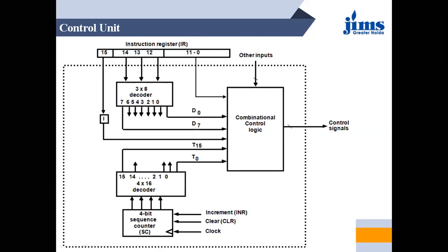See, from here, instructions register, when we are talking about the opcode, then in opcode there are 3 bits, 12, 13 and 14, and by the combinations of these 3 bits, by using a 3:8 decoder, we can produce 8 outputs. So these are different operations that we can perform.